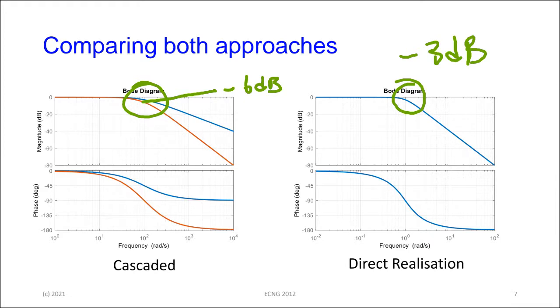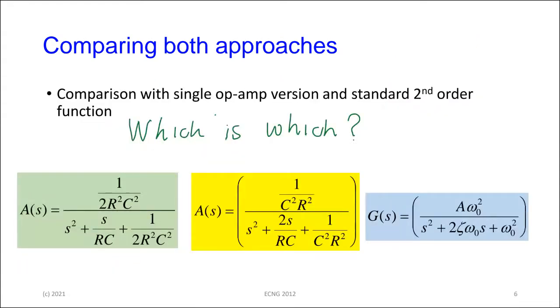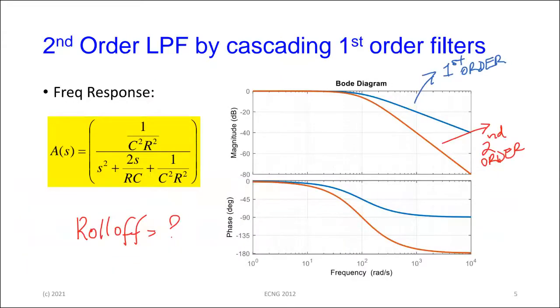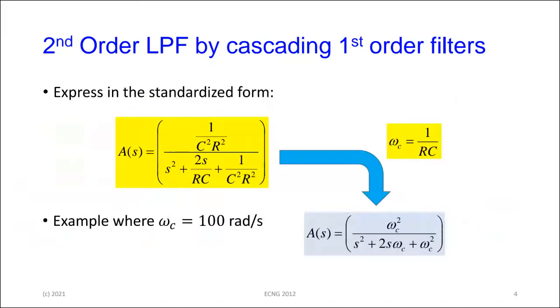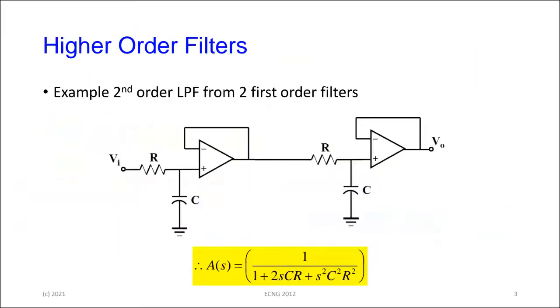So now again, you're trading off one thing for the other. This design that we just did is very easy. Just think of the approach for designing this, right? The op-amp, the two resistors and capacitors are the same, and you select them again like we did yesterday. You pick your cutoff frequency, you pick the capacitor, and you calculate the resistance value.